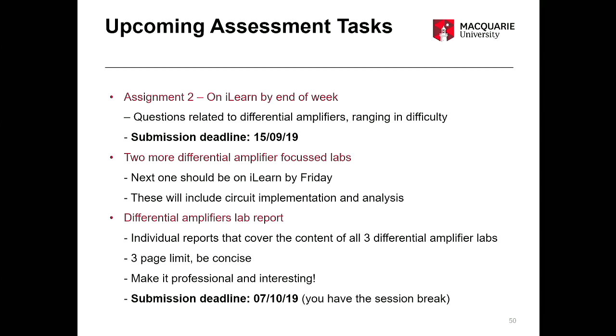But yeah, really focus on getting the circuit built quickly because I know simple mistakes can take a long time to debug. And another tip I have there is build it in sub-circuits, all right? Build a part, test that sub-circuit works how you want it to. You can also simulate the sub-circuit. You can cut off the other bit, see how that should react, make sure things are working. Because if you straight away go in with 6 transistors, something's going to go wrong, okay? There's a lot of contacts to get right.